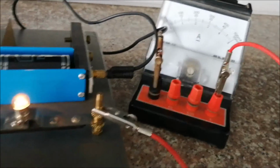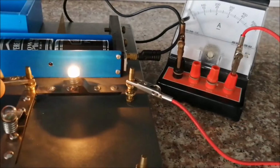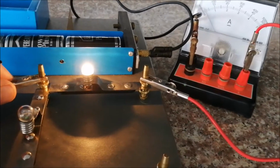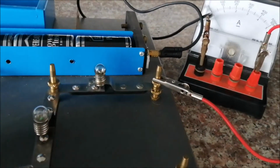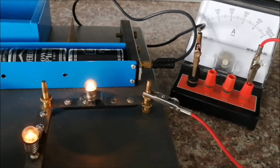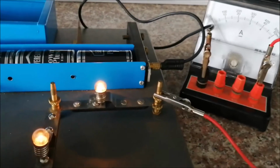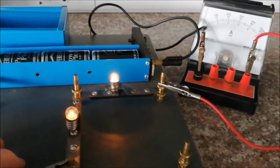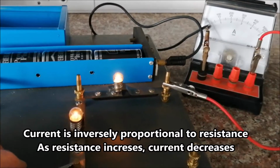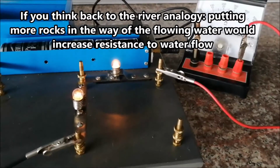So again, now we've got two globes and we have 0.1 of an amp flowing. If I change the circuit and only include one globe, you can see that we have 0.2 of an amp. So we have double the current, and by increasing the resistance, we can halve it. So the rate of flow of charge, or your current, is inversely proportional to your resistance. The more resistance you have, the less current that will be flowing. And this is a series circuit, again, because there is only one path that the current can flow.